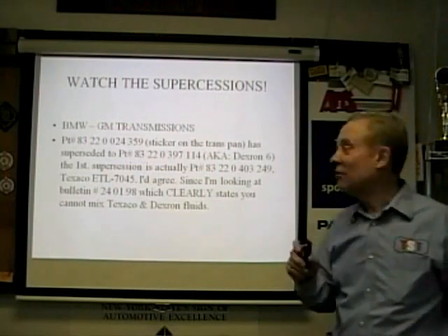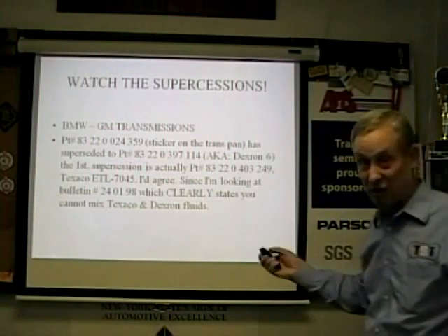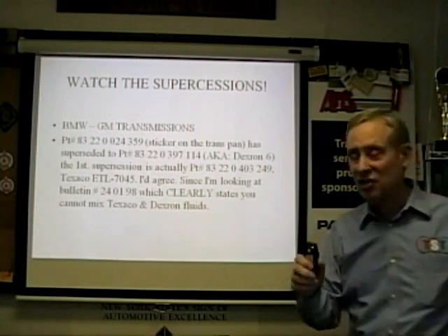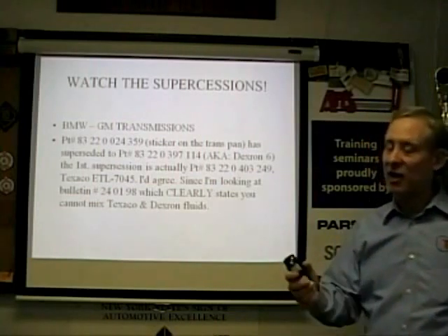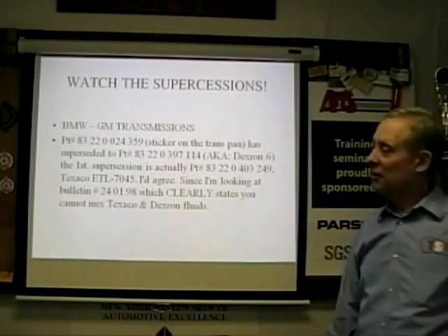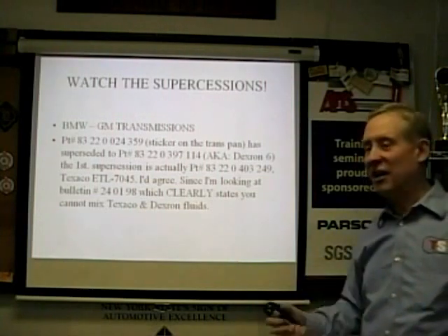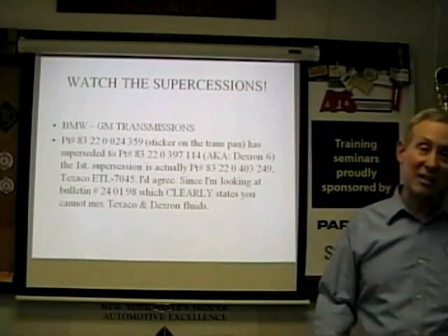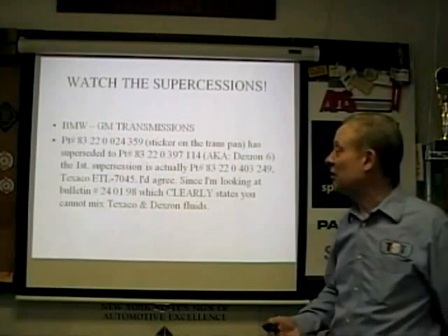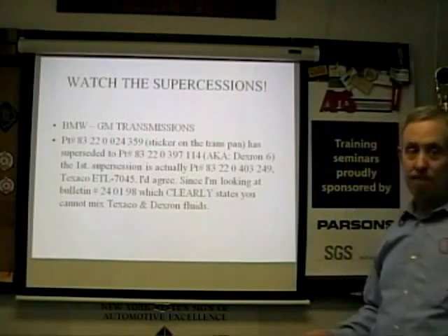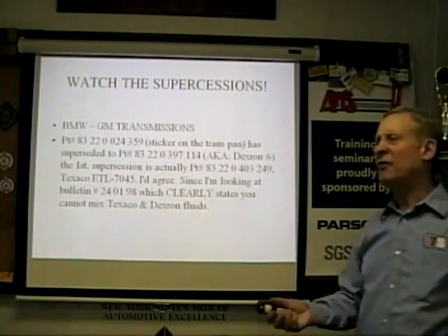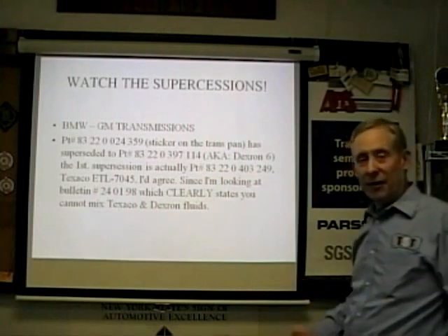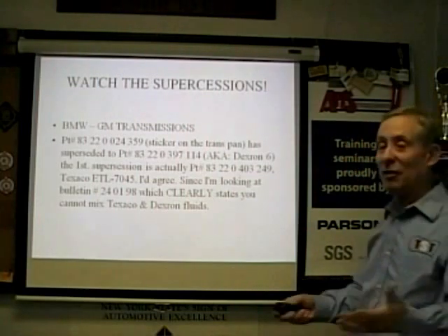So you have to be absolutely sure that if you switch it over to Dexron, which you can do, my personal car has it in there, my wife's car has the Dexron in it, you must flush it a few times. You can't get it all out of the torque converter at once: you flush it, run it a little bit, drain it, put more in, do it again, take it for a ride and make sure everything moves and pumps itself out, drain it again. You may do it 2 or 3 times to make that switch. Or you use a machine like the Flow Dynamics or a Flush It machine, which is really good. Or if you've taken the transmission apart for some reason and it's dry, that makes it easier, actually. Just more expensive. But you've already had an issue at that point.